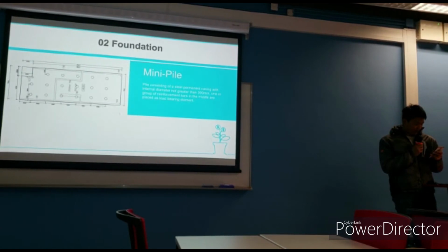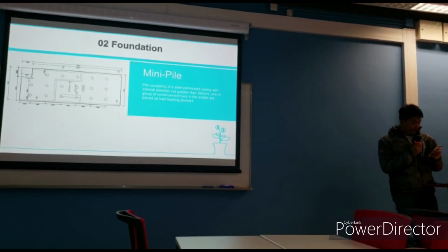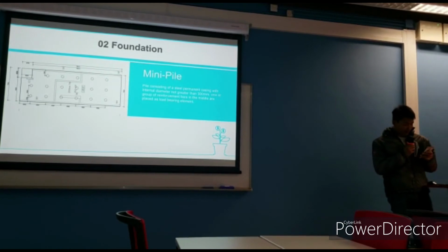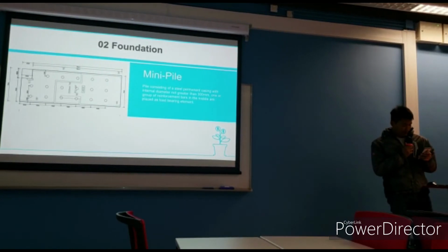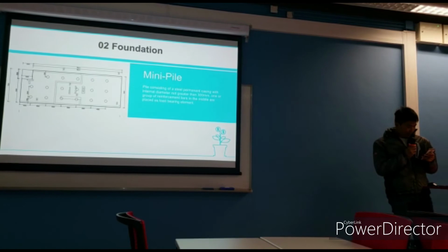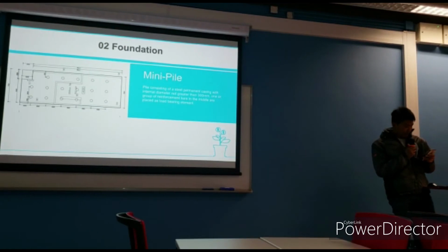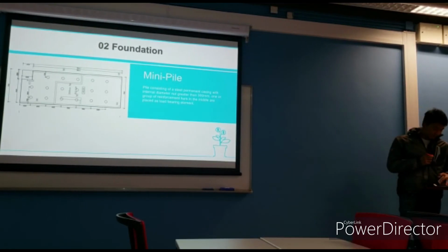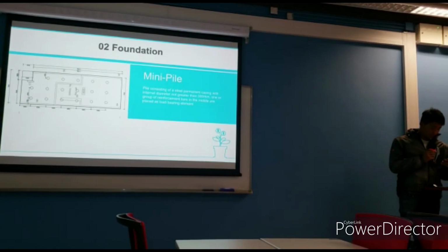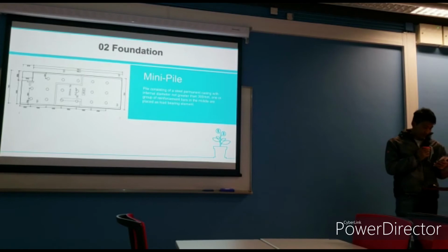The proposed mini piles are designed to support the house for all types of vertical load. The horizontal loads are assumed to be taken by the pile caps. Mini piles are installed by the use of compact drilling machines. Steel piles are inserted into the ground and grouted as piles.